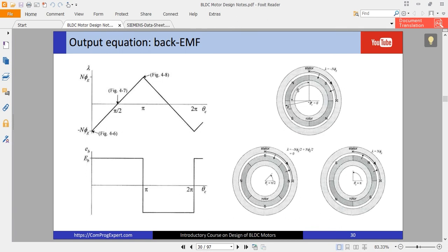This is a four-pole rotor: a south pole, north, south, and north. And we have one coil here. The span of this coil is equal to 180 electrical degrees, integral span, right? So when the rotor is in this position, total pole flux is linked to this coil, right?